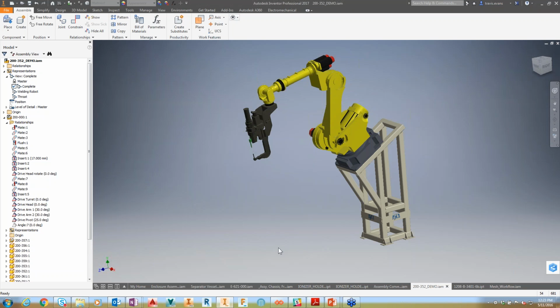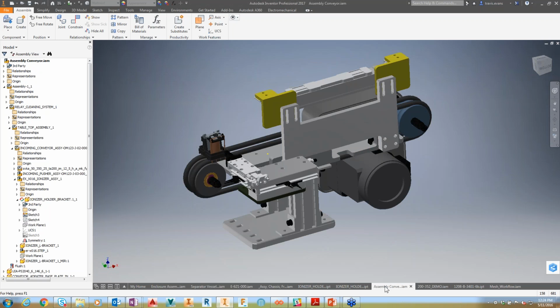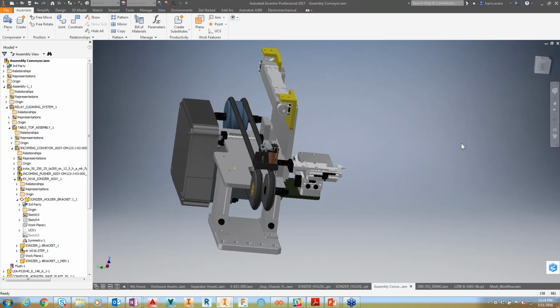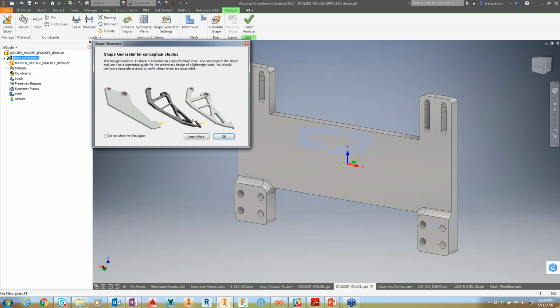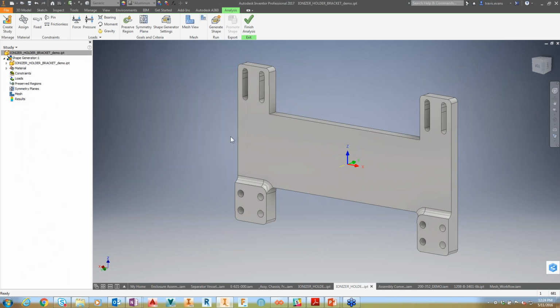It's got to support something, but maybe traditionally, just because of those mounting points, we just had it as a block because that's what we did. So taking a look at how we can change and leverage that information right inside of the tool. Shape generator technology allows us to create more data. It's going to create a mesh for us, so we can use it as a reference to make better decisions from that information. We're going to get a mesh that we can leverage and create geometry from, and then choose what we do with it.